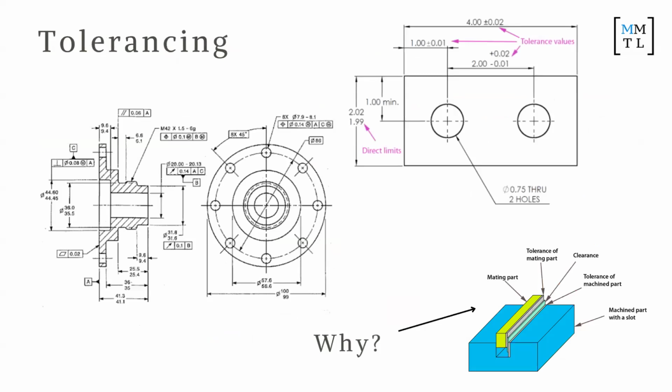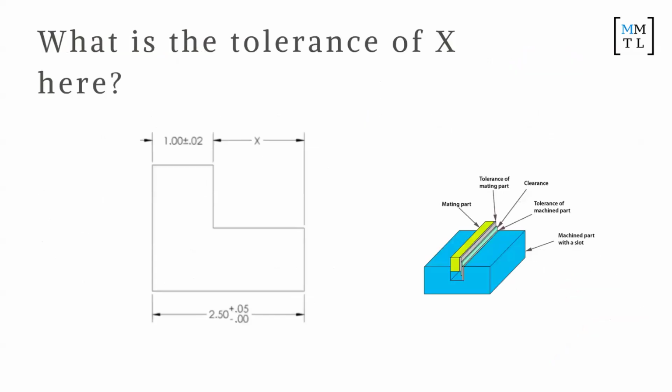And there's something else that you might see in more advanced diagrams, something called tolerancing. So tolerancing is basically the plus minus of the distance of the line. Why it's important is when we start fitting two different parts together, we need to think about maximum and minimum tolerances. We'll go a bit more about it in a second.